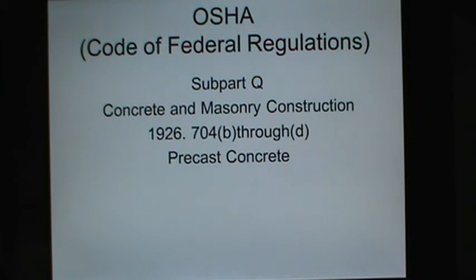704(b) says your lifting inserts have to be able, if it's anything other than tilt-up, they have to be capable of supporting at least 2 times the maximum intended load. Lifting inserts which are embedded or otherwise attached to tilt-up shall... Actually, this is tilt-up. I apologize. Lifting inserts which are embedded or otherwise attached to tilt-up shall be capable of supporting at least 2 times the maximum intended load. So this is tilt-up.